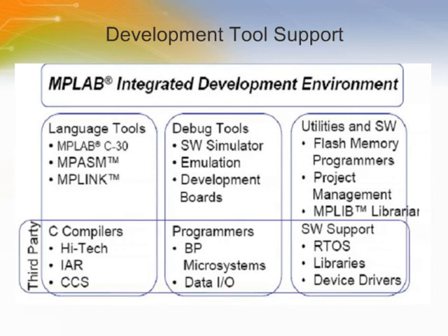Microchip's PIC microcontrollers are supported by the MPLAB Integrated Development Environment, which is used to integrate development, debug, and software utilities available when debugging code for a product. MPLAB is the only platform you will need to develop for a Microchip microcontroller and can cover products from 6 pins to 100 pins and code space from 512 bytes to 256 kilobytes.